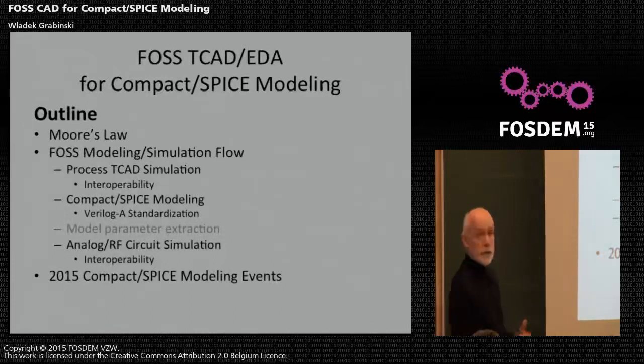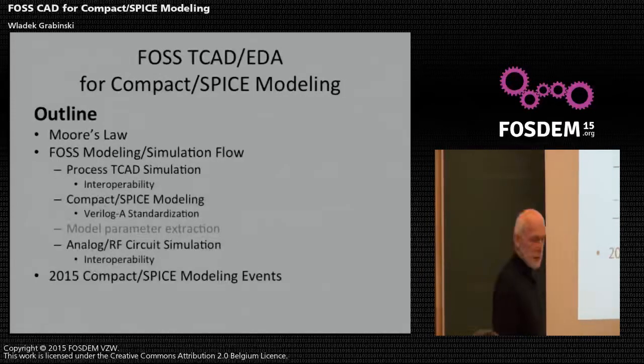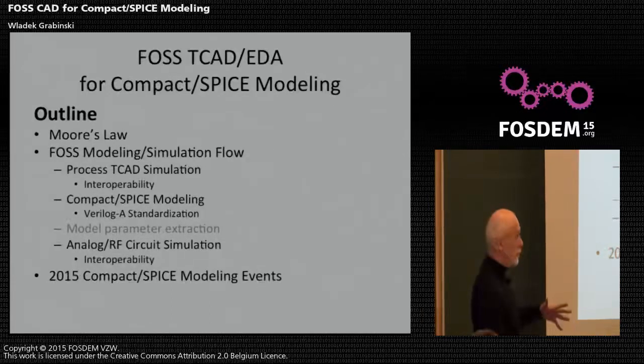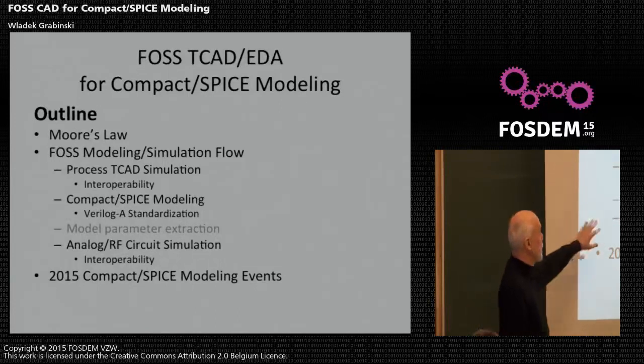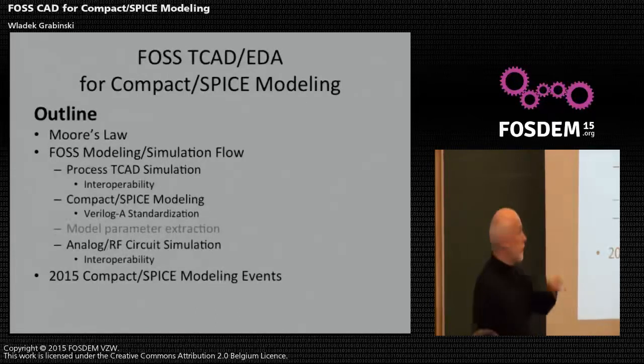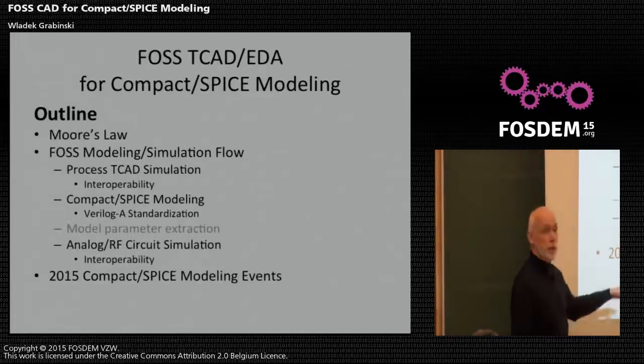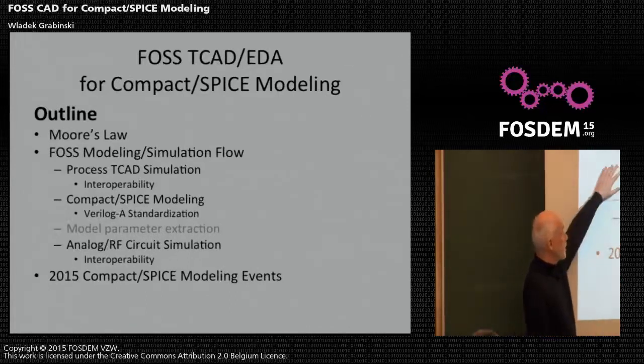I will start with Moore's law, talking about microelectronics, semiconductor devices. You cannot open a presentation without a short reference to Moore's law. Then I will go through the simulation and modeling flow to show you process and TCAD simulation, compact modeling, model standardization, model implementation. There is an important part which we are not addressing today. It's parameter extraction and library generation to interact between models or technology models and analog simulation.